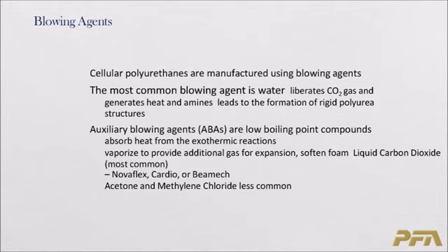By adding liquid carbon dioxide and minimizing the amount of water, you can make lower density foam without as high an exotherm, and make some softer grade foams. In developing countries, or in the lab, other blowing agents like acetone or methylene chloride are still practiced.